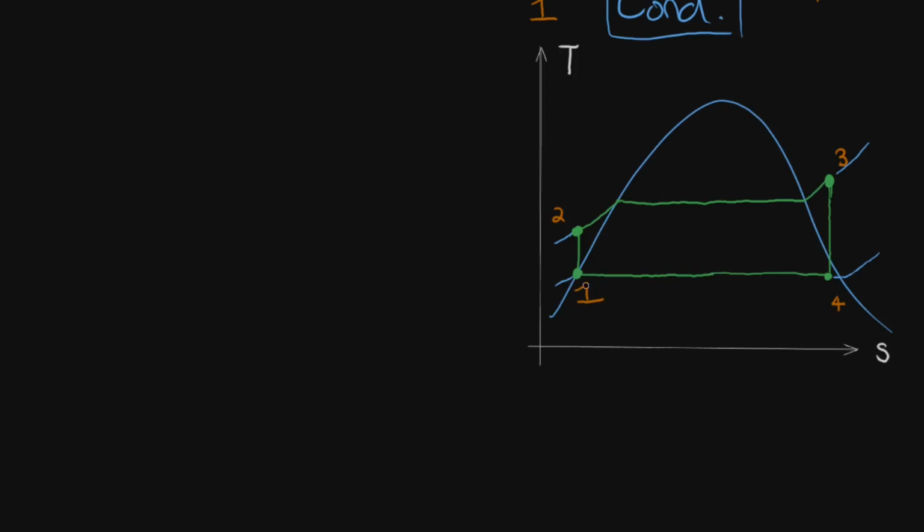So basically, for the pump, we're going to assume always that the input is a saturated liquid, because if we cool it down below that, then we just have to heat it up that much more, and it ends up not being as efficient. And if we bring it in as a vapor, we're going to get problems where bubbles form, and that can create shock waves. If you have air going into the boiler, it can start corroding. Not good. So you always want to send saturated liquid into the pump.